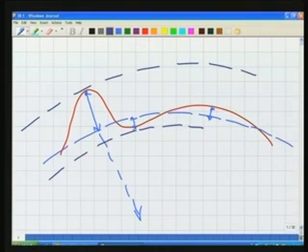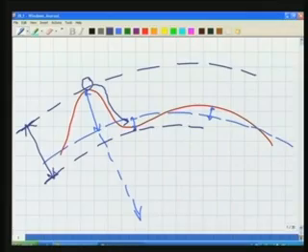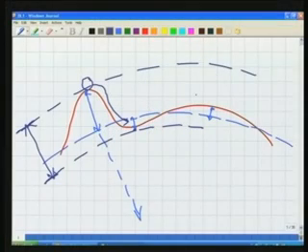equipotential surface passing through this, and as we see, if we put a water droplet here, it will flow in this direction, because this level surface is higher than this level surface. So what we say is this point is higher than this point by this amount. So the difference in elevation between 2 points is the separation of level surfaces which are passing through those 2 points.